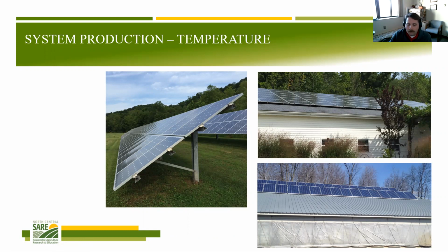We mentioned tilt. We're going to get into the details of tilt in a couple of slides here, but temperature is also another influence on solar, where if you look at a spec sheet on solar, it will give a temperature coefficient for voltage and power and current. And in particular, you'll note that if you can interpret that coefficient, it's that as we increase cell temperature, we decrease power. So they are less efficient as they get warmer.